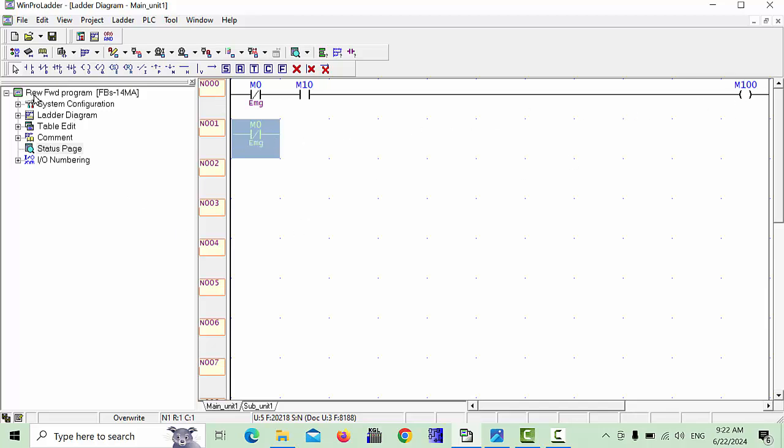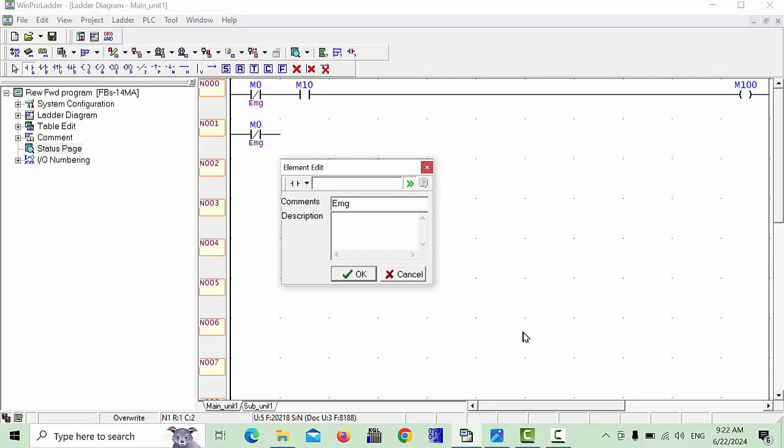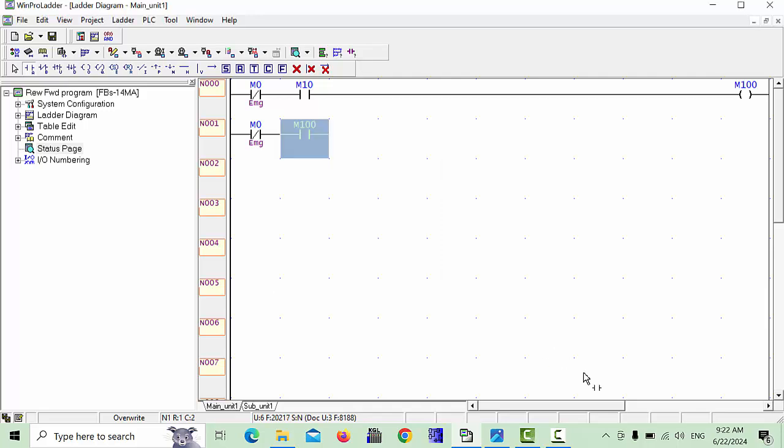And you have to use this throughout the complete program. When your program stops after the last line, until then you have to use M0. This M100 when you start, I will take it here from the M100 switch. M100 is my program execution.